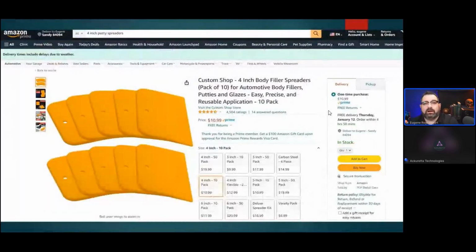If you are keeping your resin in the vat for longer than a day, you need to mix that resin in the vat. Now you can use something like a business card or a credit card, or these things right here. They're filler spreaders for the automotive industry, and they're really inexpensive. Like a 10 pack is like $11. The 4-inch one works really well inside the SOL. So I'll just put it in there and mix the resin back and forth to make sure you spread it evenly,